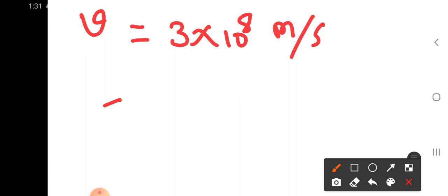Okay, in actual practice, because of the resistance and leakage of the lines, the velocity of the traveling wave is slightly less than the velocity of light. Normally a velocity of approximately 250 meters per microsecond is assumed. Yes, it can be 250 meters per microsecond.